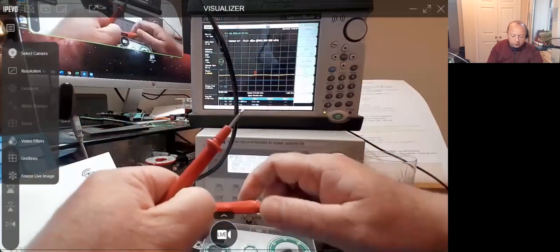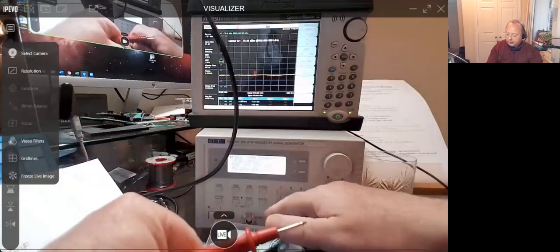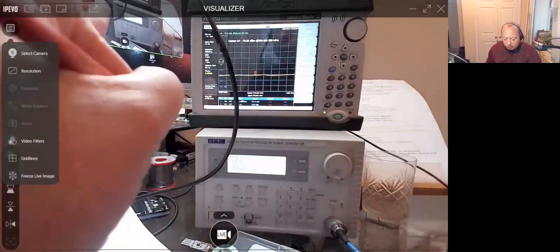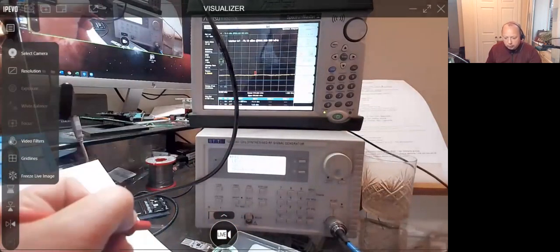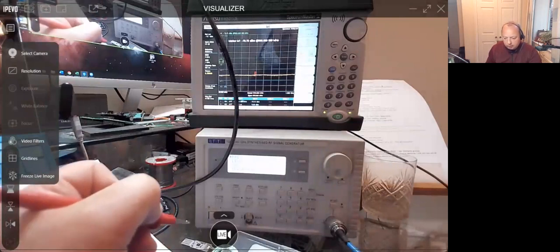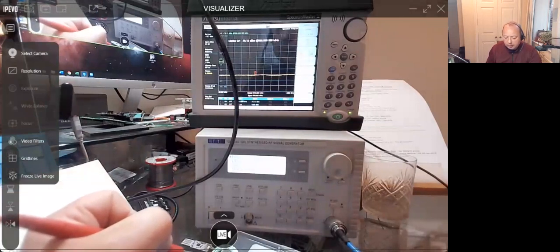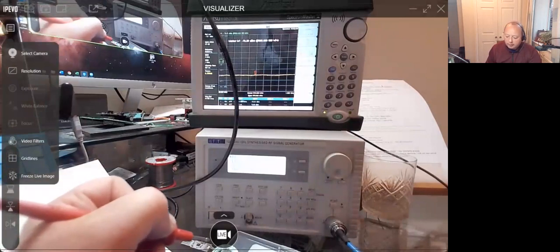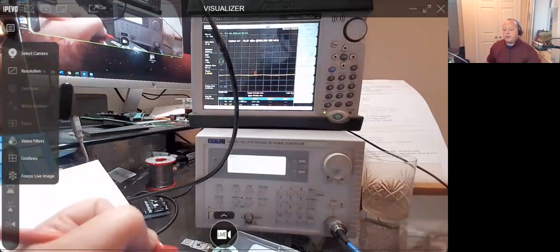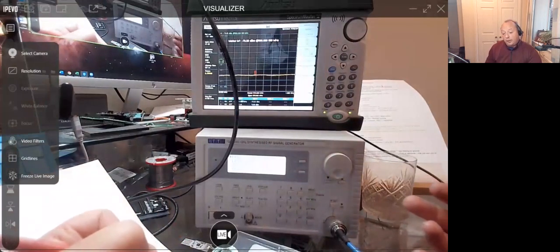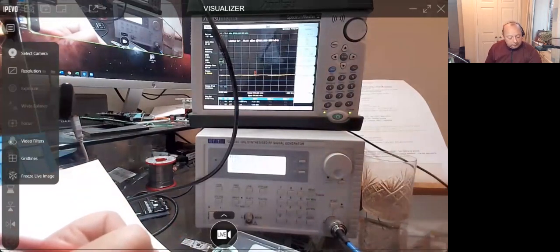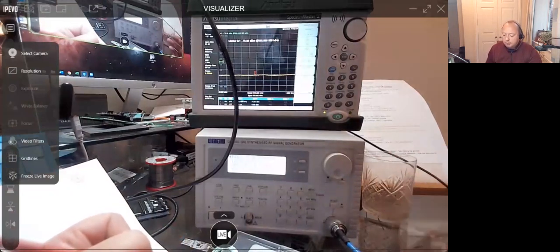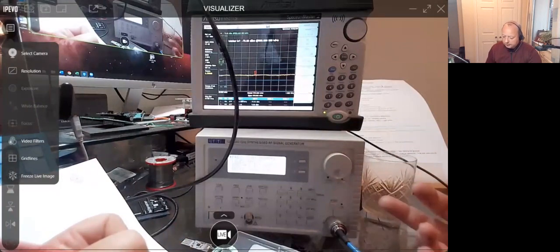And of course, you'd obviously have a ground, so you could connect a ground to your board. And the idea is you go around your board and inject noise into your electronics and see if the electronics will misbehave. So, for example, it might suddenly do a reset. That would be a problem. And it wouldn't be anything you'd done wrong in the code or your logic. It would just be susceptible to a frequency.